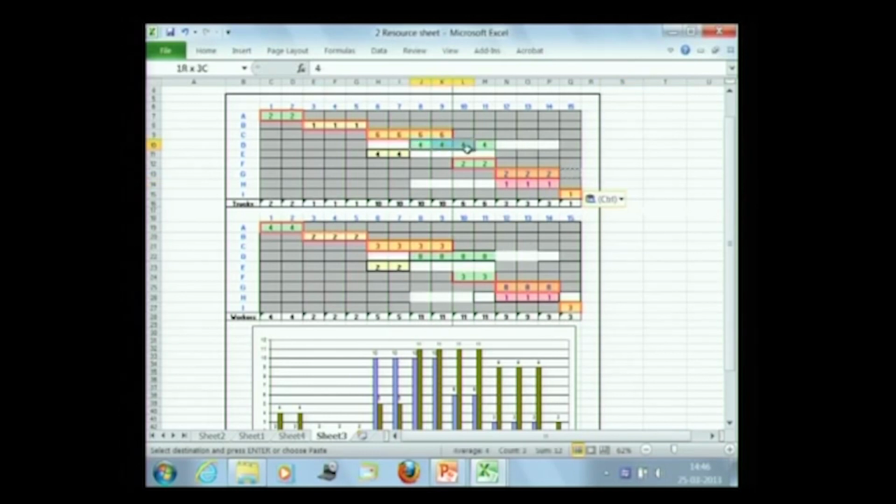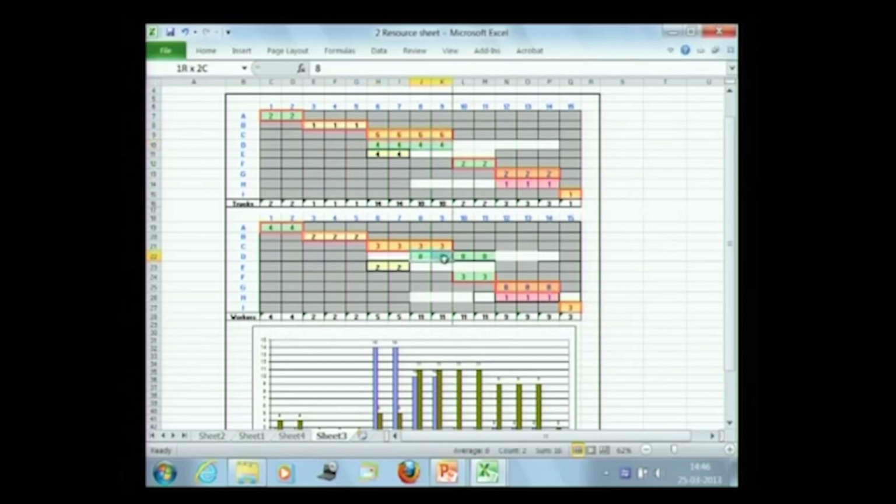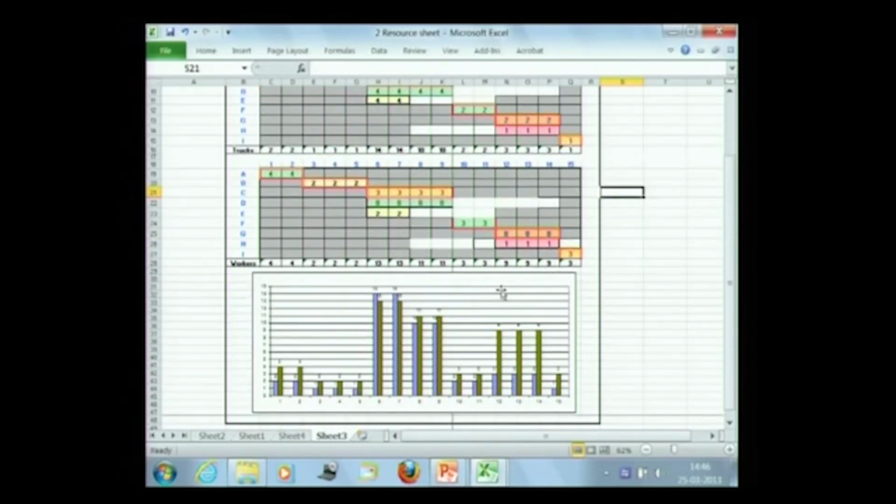In the early start solution, what did I have? I had D here, and I have to go down here and shift D2. In case I forget to do that, remind me. This is for each of the resources, and we had 14 trucks and 13 workers. My truck is over allocated because I am only allowed 10.